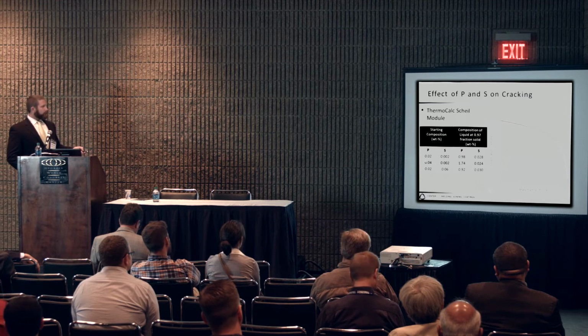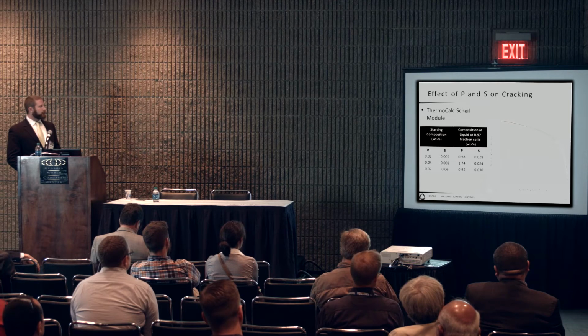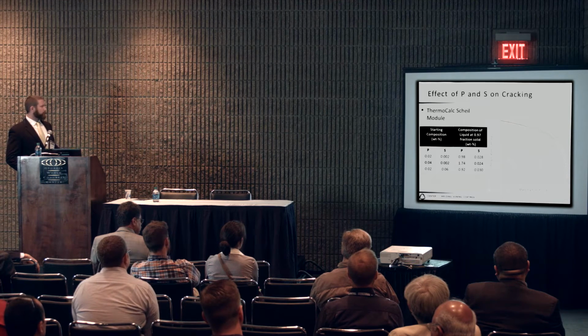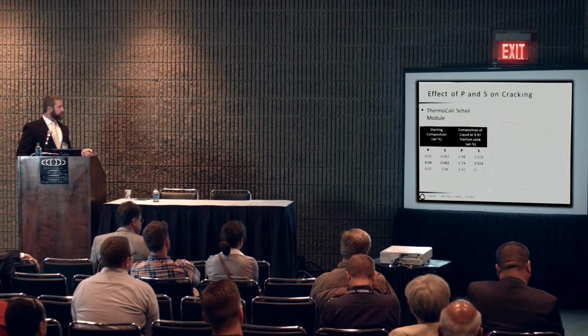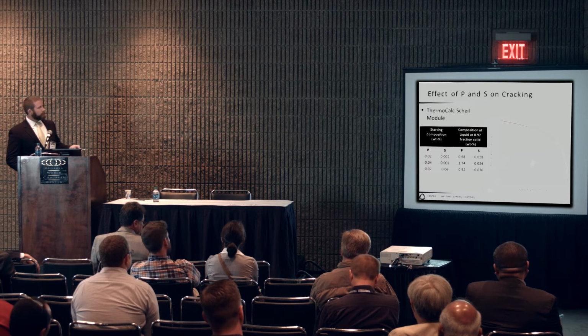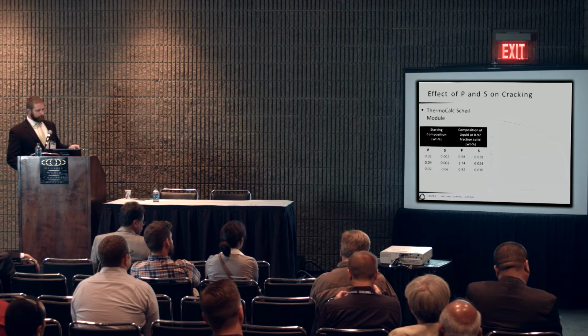And then as we increase the phosphorus level, the phosphorus in the final liquid to solidify jumps significantly, like we'd expect, and the sulfur remains the same or decreases slightly. However, the interesting one is at high sulfur levels with low phosphorus: we see similar levels of phosphorus enrichment as the minimum impurity content composition, but the sulfur doesn't increase significantly in the final liquid to solidify. And that's due to the manganese sulfides being formed starting at about a 0.4 fraction of solid.